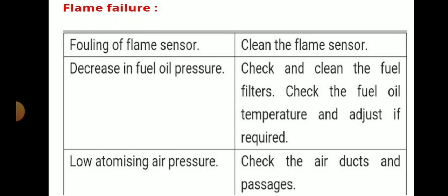Decrease in fuel oil pressure means check and clean the fuel oil filter, and check the fuel oil temperature and adjust if required. Low atomizing air pressure means check the air duct and passage.